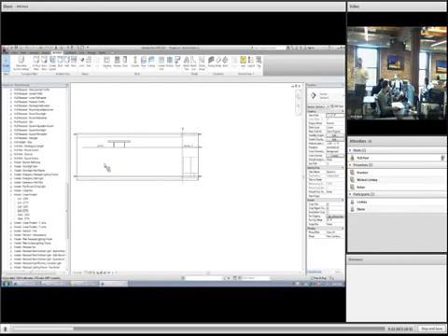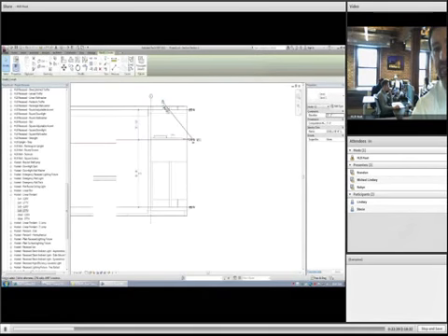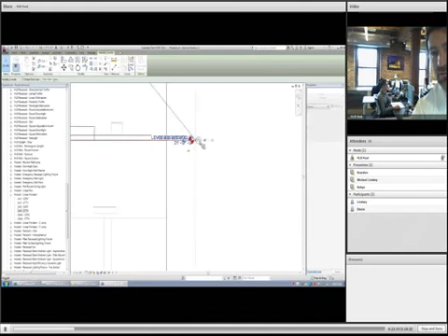The nice thing with the levels is you can drag the ends out as a group. This is what Robin's experiencing. She's seeing this lock box right here when she selects her level. All that is saying is that the ends are locked, so if you drag them out, they all move together. Does everyone see how that's working?